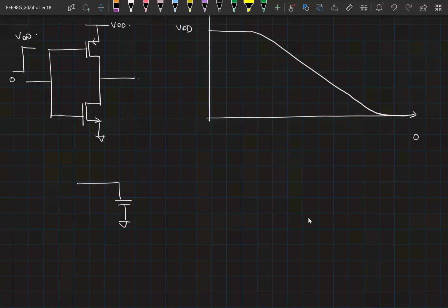So I can model it as some current which is getting pulled out of the capacitor. But now because the NMOS transistor has thermal noise, you also have some IN square here, because we are again looking at the PSD. So to understand this, you can simply think of some IN here. But why is current only pulled out? IN can be positive and negative.